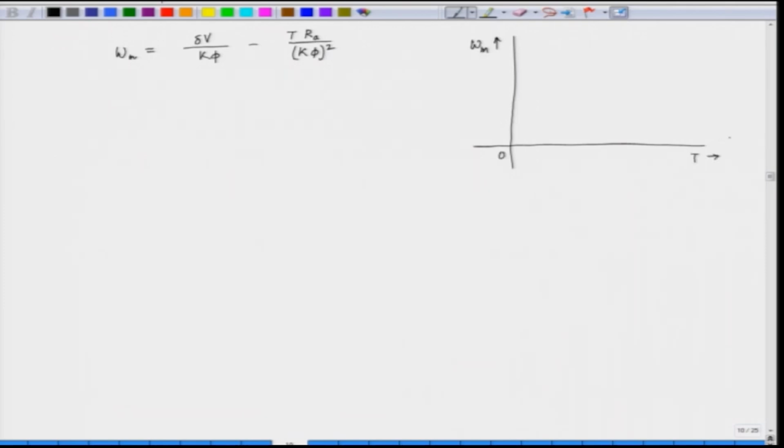To control the speed we have to vary the duty cycle, that is delta. So, if we go on plotting this, this is for one value of delta. Then we have another plot for a reduced value of delta, which further decreases and so on.